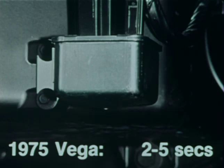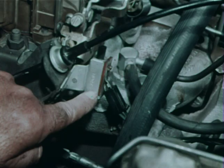1975 Vegas employ an AC control module that prevents compressor operation in the event the engine overheats. The module also prevents compressor engagement when the engine is cranking. Finally, a wide-open throttle cutout switch is employed to cut off clutch current when full engine power is required.